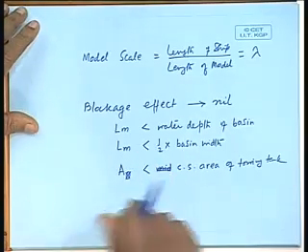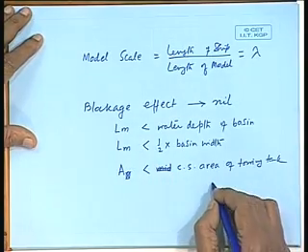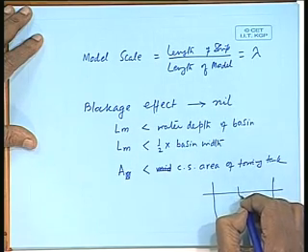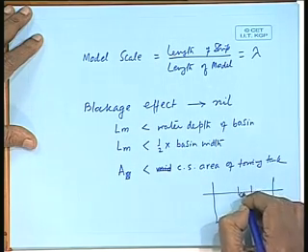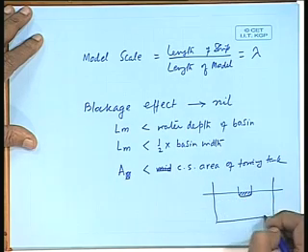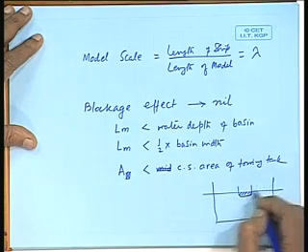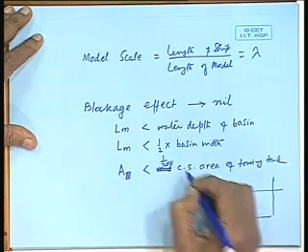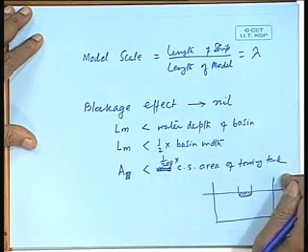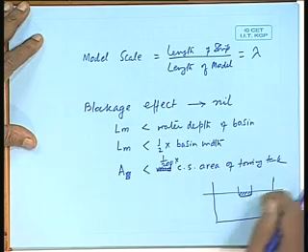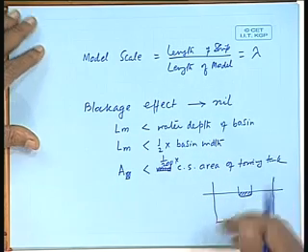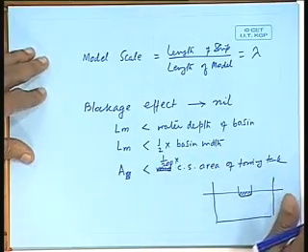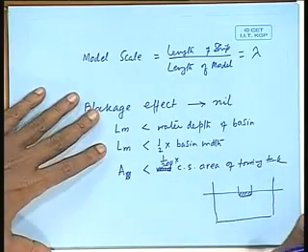So, the midship area of the ship, that is, if this is my tank, this is my water level, the model midship area, this area should be 1/200th or less of the cross sectional area of the towing tank. That is, total cross sectional area of the tank divided by 200, that my midship area should be less than that. Then I can assume there is no blockage effect.